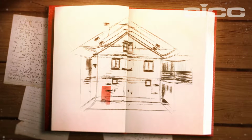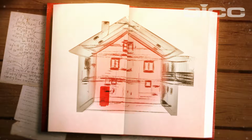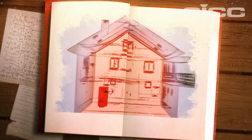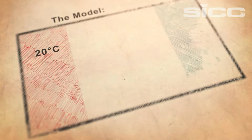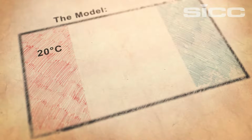A building with a heating, surrounded by a shell. The heating produces heat which disappears fast or less fast through the shell outside. The U-value theory describes a model in which the inside of a shell is warm, for example 20 degrees Celsius, and the outside cold, for example -5 degrees Celsius.